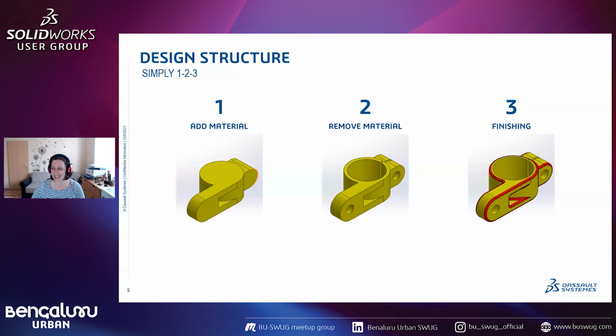Yeah, totally. I think it will help many of the people here, and also who will be watching the recording, because I always suggest that if you are adding a design fillet, please do it at the end, because if you suppress one thing, the rest of the design is going to mess up badly. But this explanation was really great. The machining fillets, why they should be added, and also the design, the finishing fillets, why they should be added at the end.